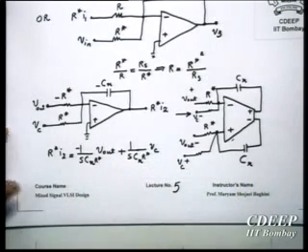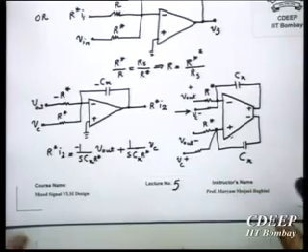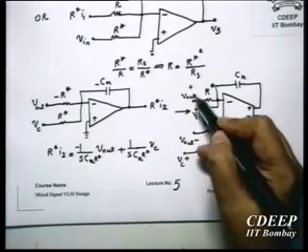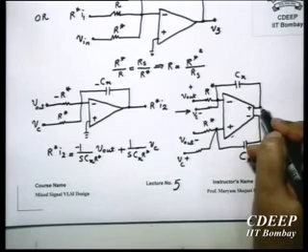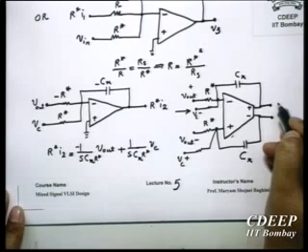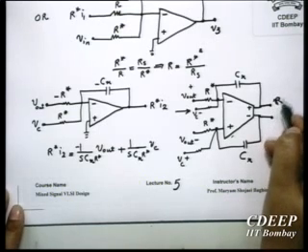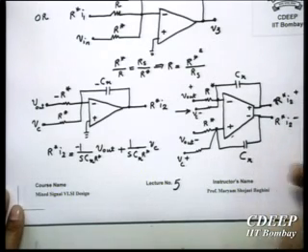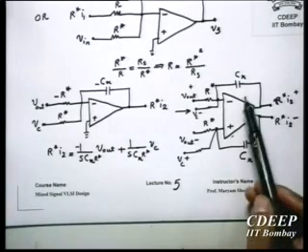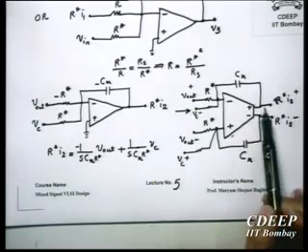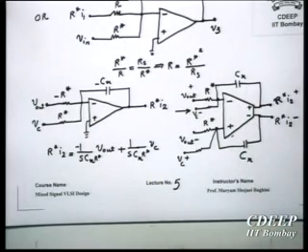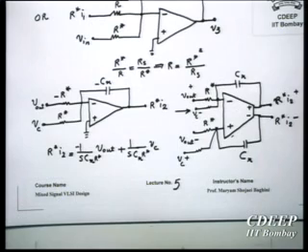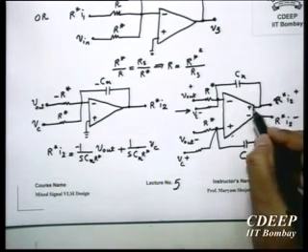into VC. Okay. So now if you look, first you look at V out, okay? So this is V out plus, this is V out minus. Now this is what I get at the output, and this is R star I2 plus, this is R star I2 minus. Now if you look, the gain from this node to this node is minus R star upon SCX. Do you agree? This is positive, this is positive. Right? I am taking this as an output.